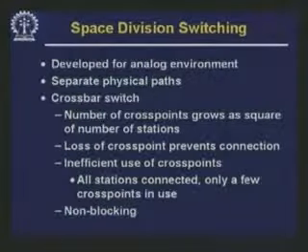So let us first talk about space division switching. It was developed chiefly for the analog environment. And why do we call it space division? Because the different calls go through separate physical paths. So that is why they are called space division switches. Unlike time division, where different calls may be going through the same physical path in different time slots. We will come to that when we discuss time division switching. But in space division switching, different calls go through separate physical paths.